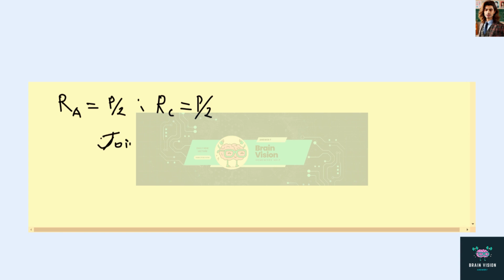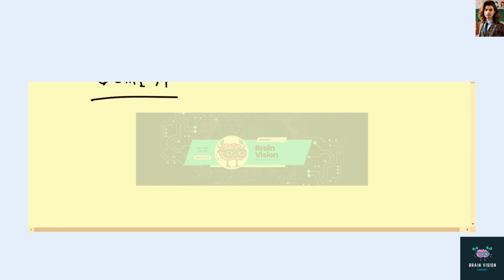So let us look at joint A. If you look at joint A, you will discover the forces. There's this force here, and this force coming. Now, this is our joint A. You are going to determine the angles using the information given in the question. Because it's coming out of joint A and going to another joint B, call it F sub AB.